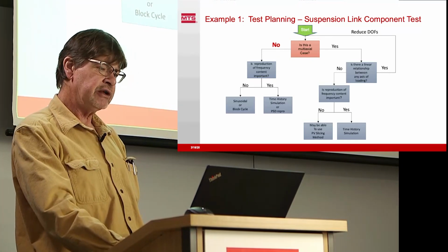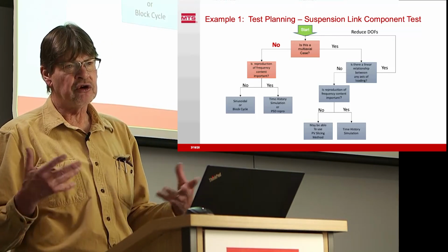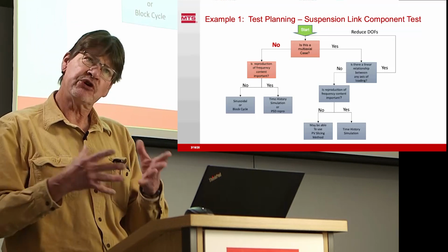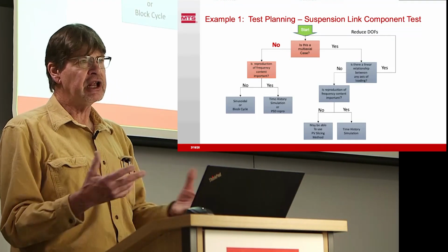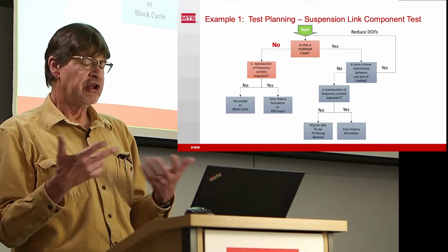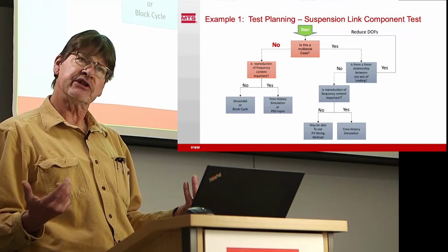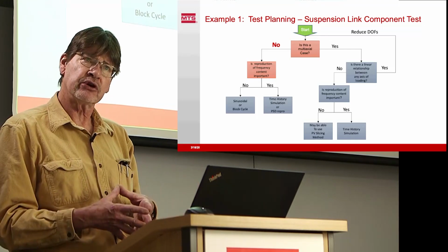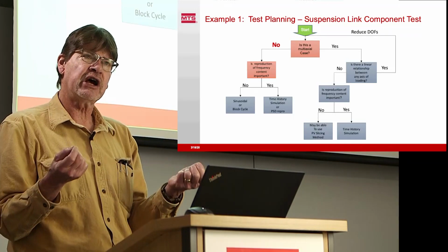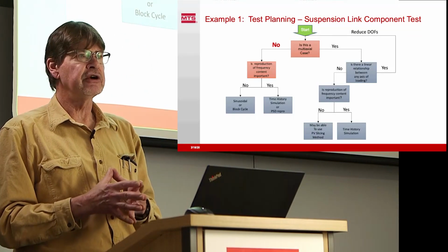So good, all right. Then is the reproduction of frequency content important? Do I have to get the real data and the real wave shapes? Well, I would if I had the elastomer bushings included. Without the elastomer bushings, I'm testing primarily just steel or aluminum. They're not very sensitive to the loading rate or frequency. So then we could accelerate the test much faster and get it done in a much shorter time. Boom. We can learn the most in the shortest time if we can do it like that, if that focuses on the right area for us.